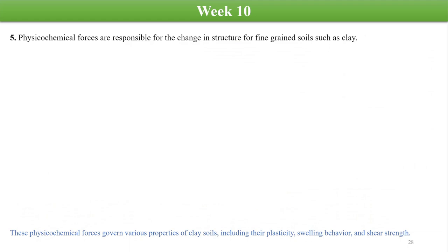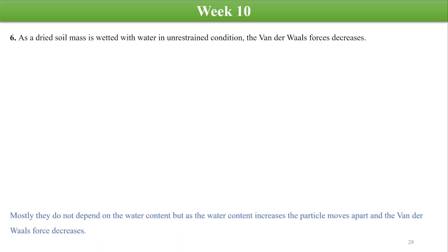They mainly govern the properties of the clay, because the particles in the clay are in the short range, very close to each other. So physiochemical forces govern various properties of the clay soil, including the plasticity, swelling behavior, and shear strength. Right, so in this way you can answer this question.